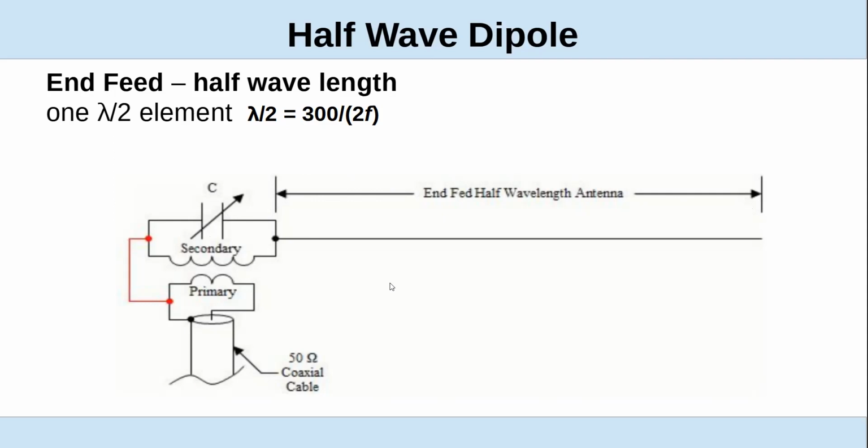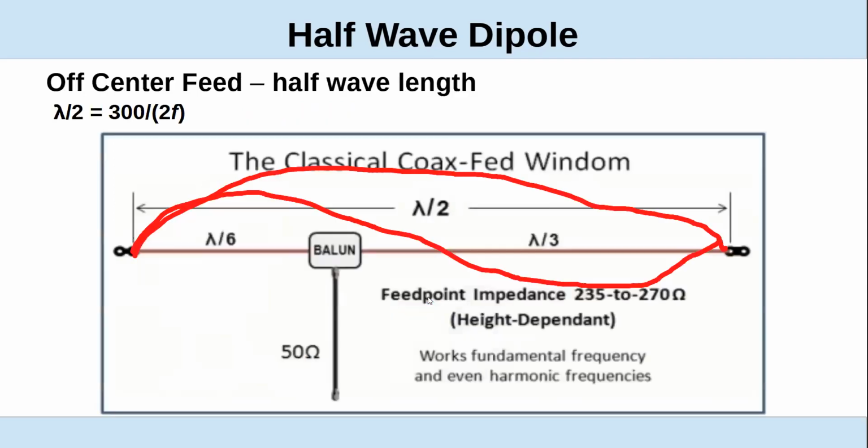You know, if you do a parallel fed wire, ladder line or window line, loss from mismatch, high SWR, is very low. And so you can be very frequency agile with the antenna, as long as you have a tuner that'll handle the mismatch.